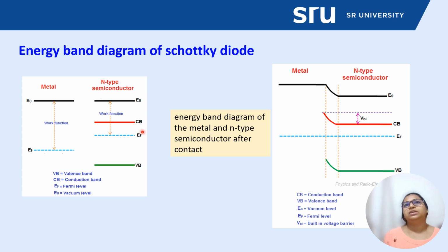One of the important characteristics of the Schottky barrier is the Schottky barrier height. That barrier height depends on the combination of the semiconductor and the metal. As we discussed in the last slide, when the barrier height is for an ohmic contact, which is the non-rectifying barrier, it is very low, whereas the Schottky barrier height for a non-ohmic contact is very high, which is also known as the rectifying barrier.